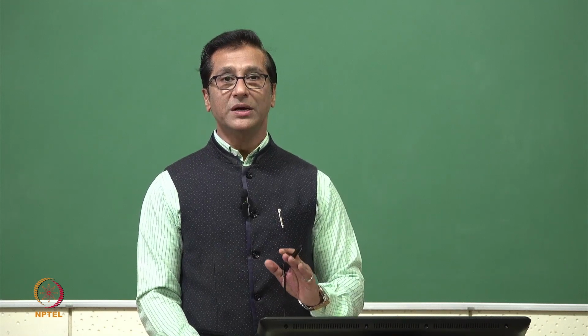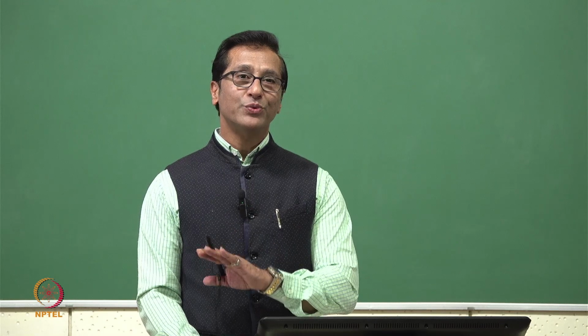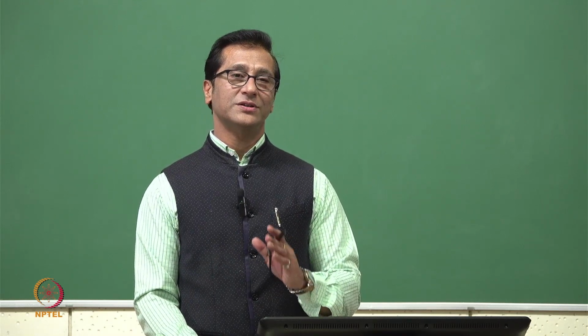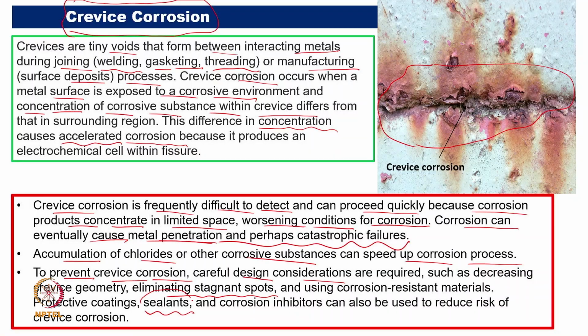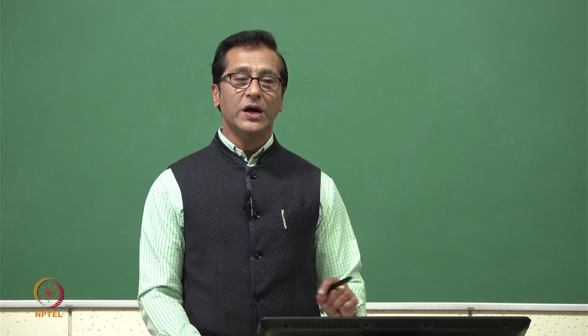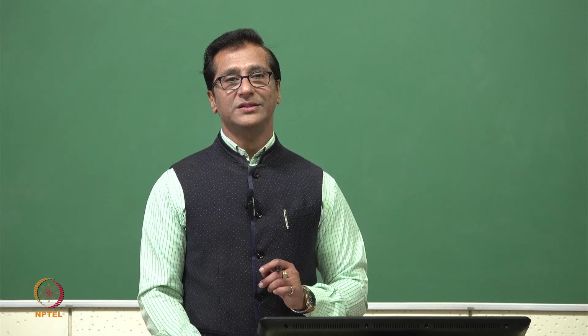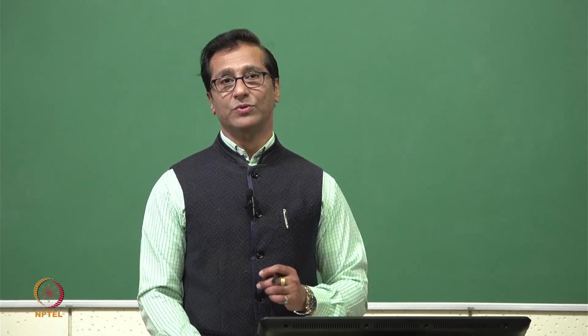Even though sealants are not going to handle stress, they can prevent ingress of this contaminated or polluted water, or maybe say water ingress. That is going to help. Many times people ask, why do we use a sealant? To avoid ingress of this kind of moisture or acid, which creates a problem.